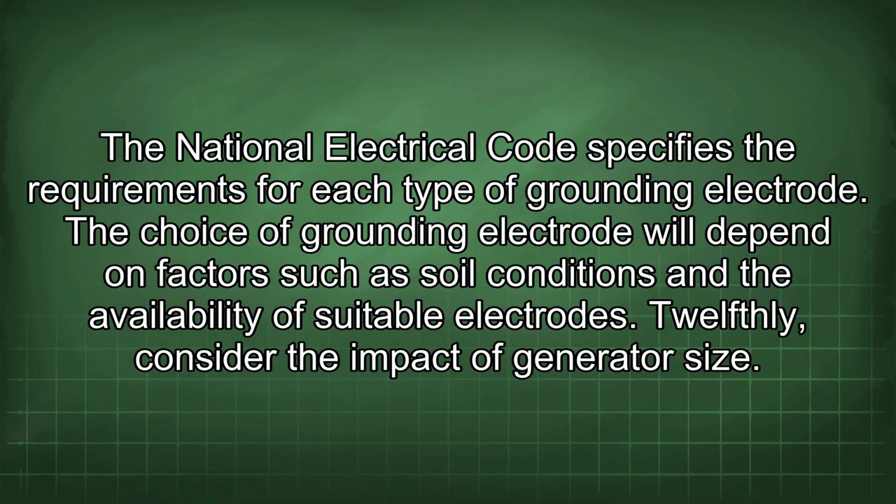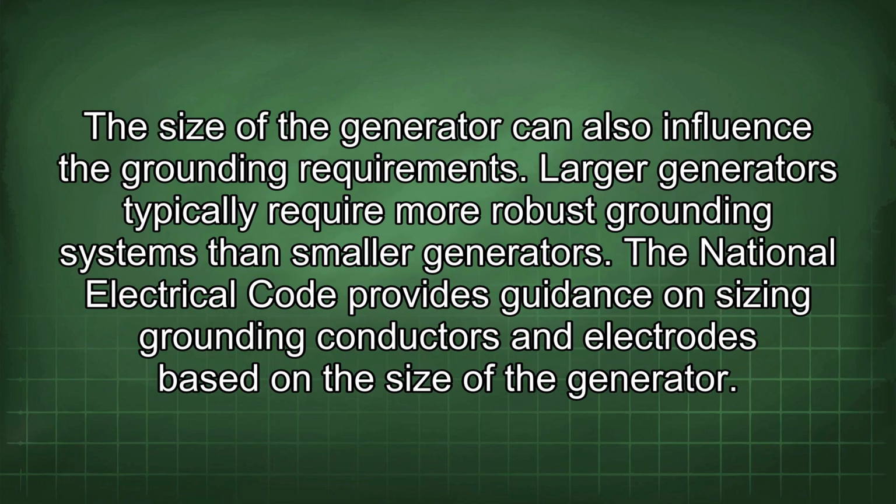12thly, consider the impact of generator size. The size of the generator can also influence the grounding requirements. Larger generators typically require more robust grounding systems than smaller generators. The National Electrical Code provides guidance on sizing grounding conductors and electrodes based on the size of the generator.